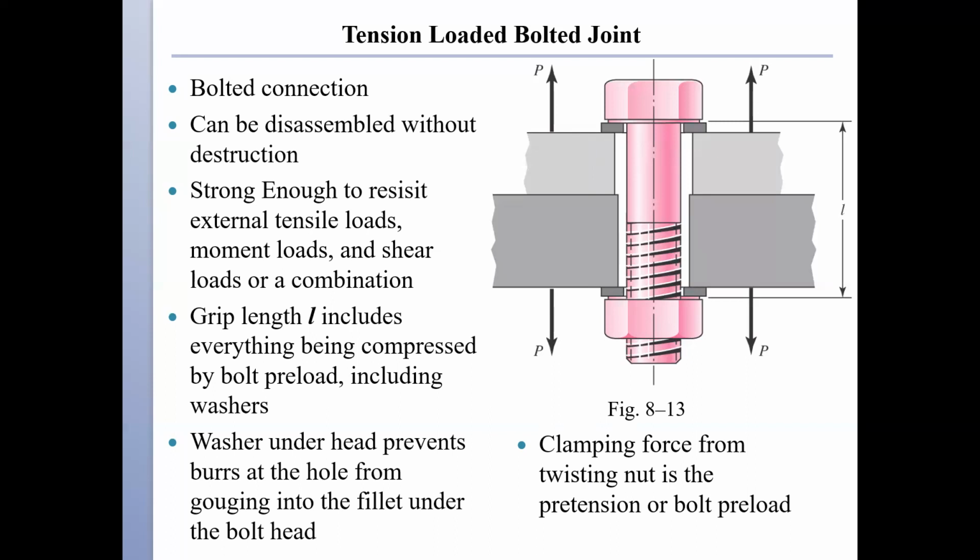How about the bolt itself? When I tighten the nut, I'm really stretching it. So the bolt is in tension. We refer to this clamping force as the preload, the pre-tension, or the bolt preload. So this is even before we apply this external load P.